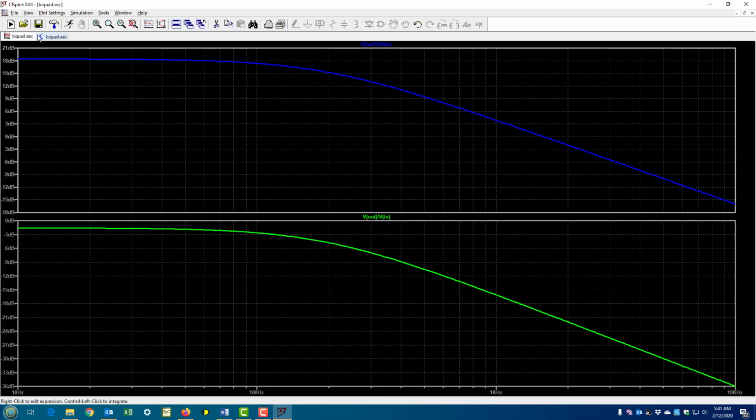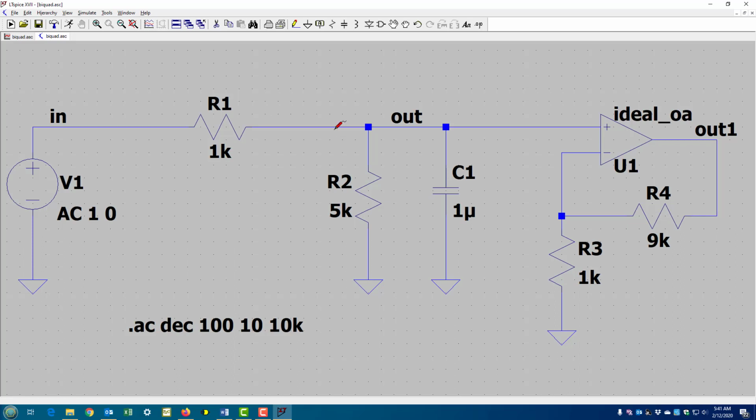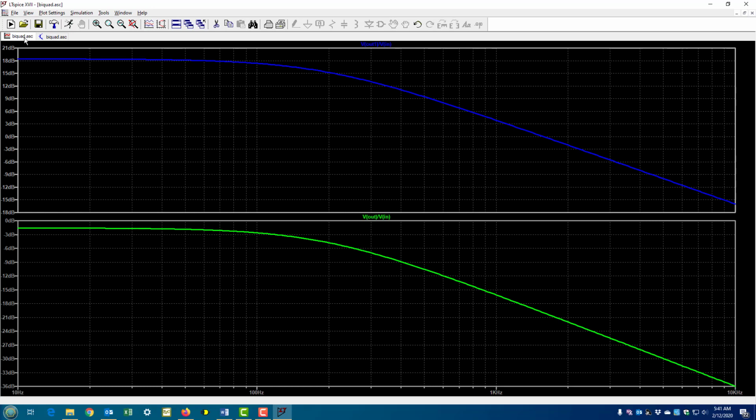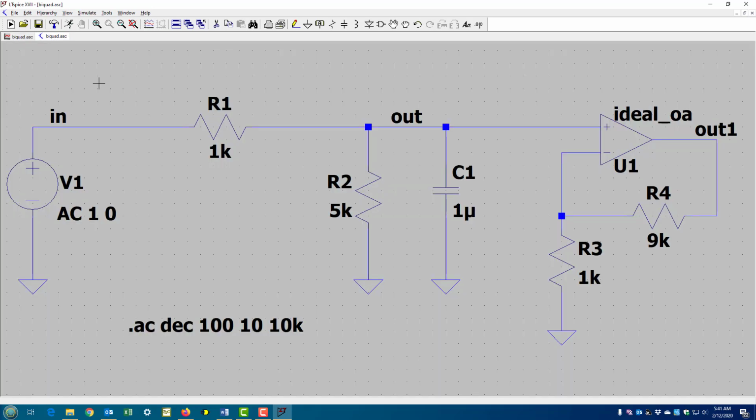Let's just go to our graph, for example, and you should change the background to be white. If you choose the background to be white on both the plot and the schematic, I think you'll get a lot better results when you copy them into Word. This is just my typical suggestion.